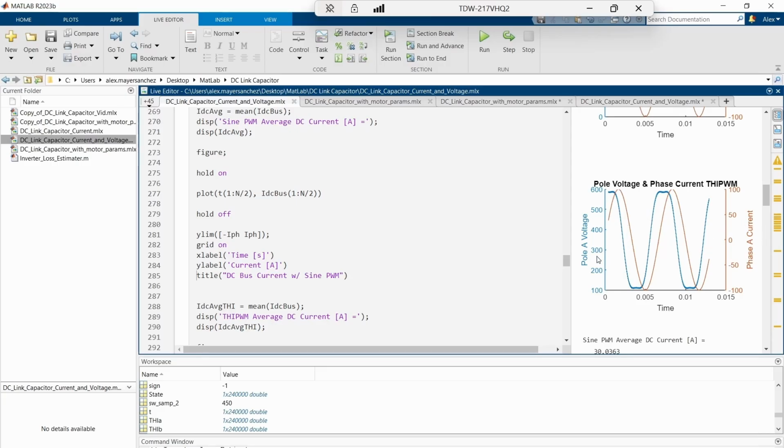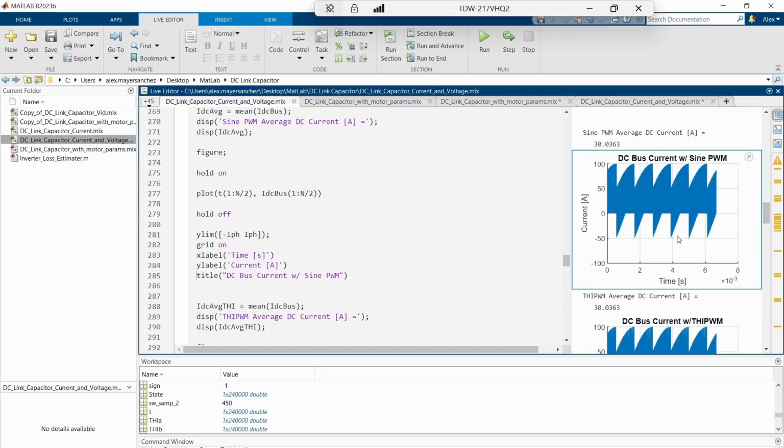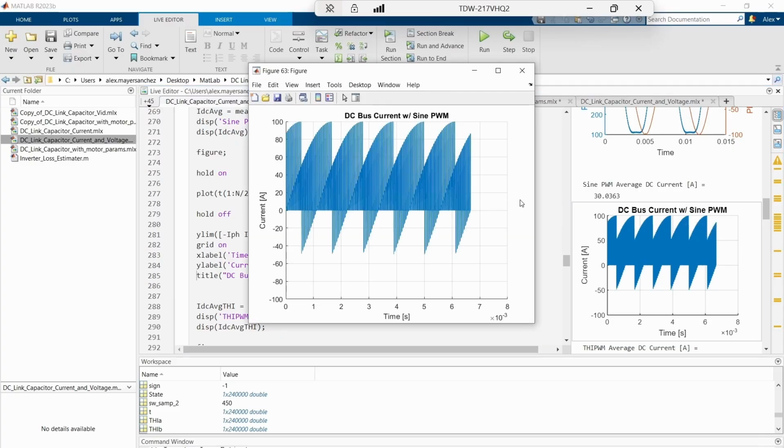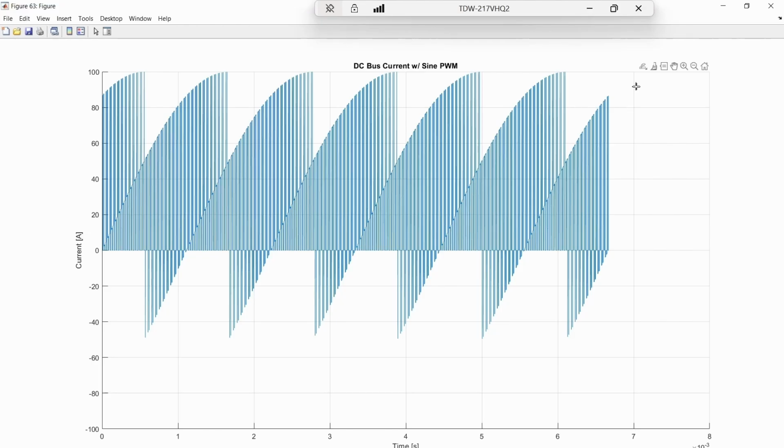So if the power out has decreased, then the power in also has to decrease. And the power in decreases by supplying a negative current. And this would be really bad for the battery, because if you imagine the current going in and out of the battery, having this AC component in the battery will heat up your battery, and eventually, if it's bad enough, it'll probably blow up your battery pretty much.